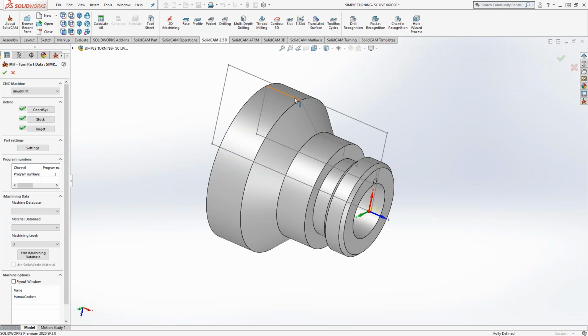So you never really need to do anything like configurations with turning, unless it makes it easier to generate this envelope. But with a milled part, if there's some turned features to it, you don't have to bring in a turned version of the solid and then do a milling program on a milling part. You can actually do everything on that same part, and when you bring it into the turning modules, it will spin it around the rotary axis and give you all the outside edges of the part. Does that make sense?